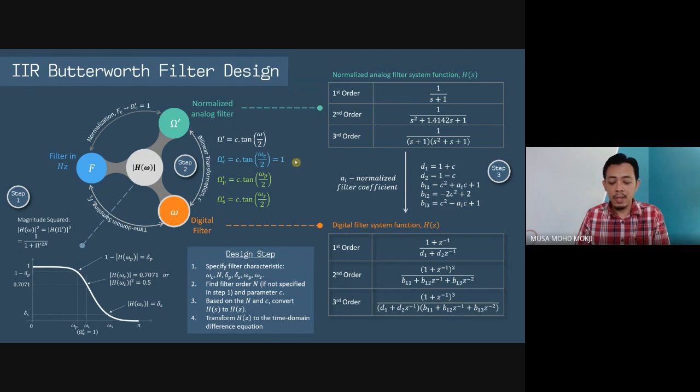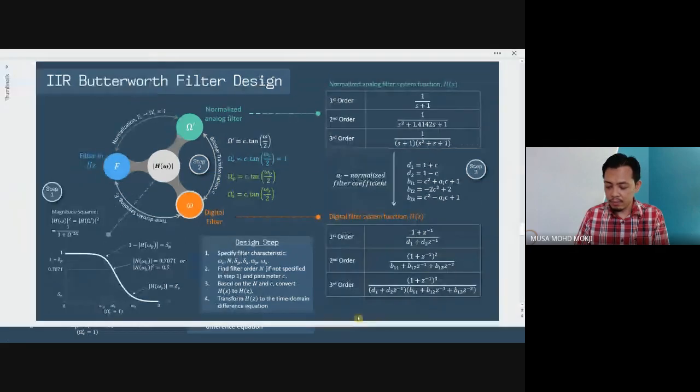That's why we solve the difference equation instead of doing the original convolution. Theoretically, the difference equation is actually convolution, but it is a more practical form of convolution for an infinite summation. If you do the normal convolution, you cannot do that. Only FIR can do it.